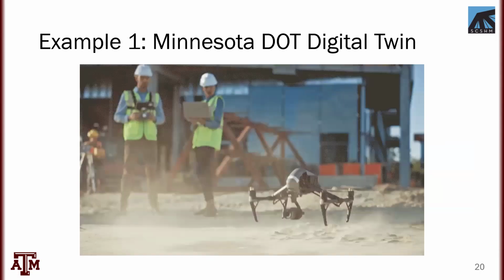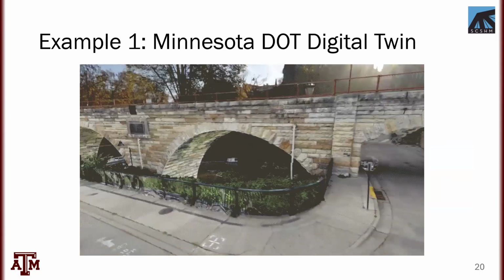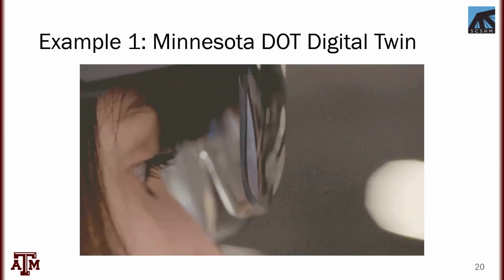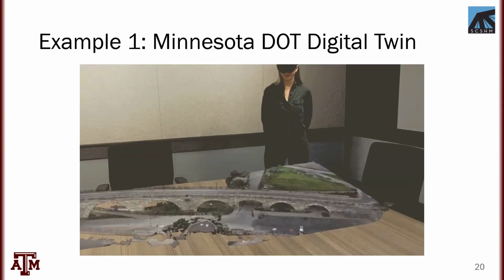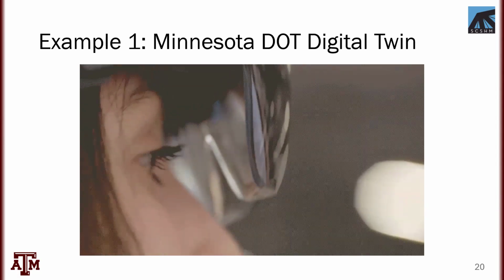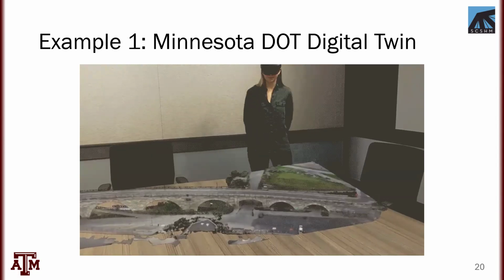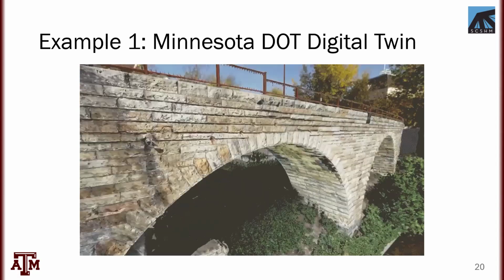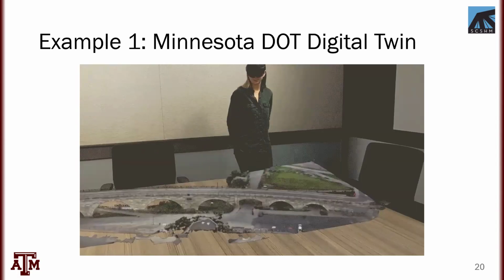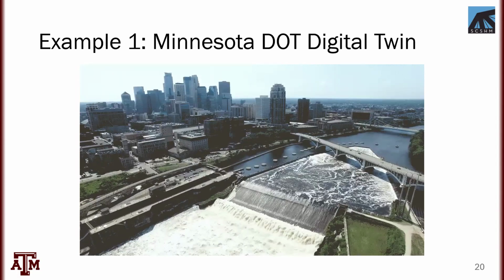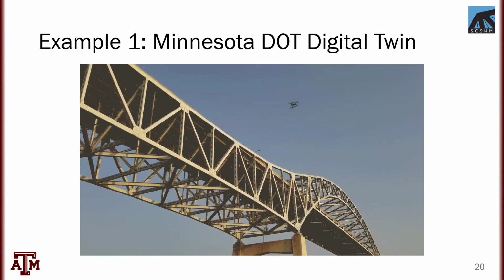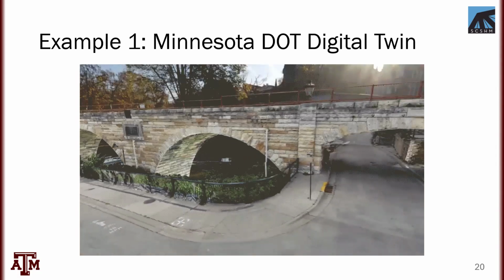They performed photogrammetry, developed this digital twin workflow, and they concluded that with this approach, they can cut inspection hours by 30%, they can reduce fuel time, they can reduce traffic disruptions, and also improve safety and reduce risks. Their approach was also augmented with AI-powered defect detection. So things like cracking, spalling were detected using AI and machine learning for pretty much streamlining the inspection process, making it a lot faster and accurate.